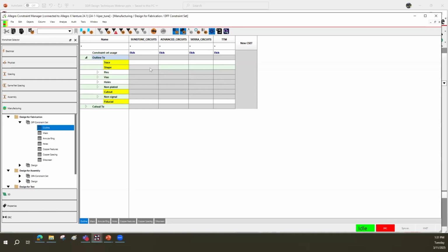Now, I've been around a while. I can remember days where I'd send my board file off on a Friday, expediting. I wanted to work on it over the weekend, only to come in on a Monday morning to open my emails and find a laundry list of things I didn't follow. It was their rules, their minimum requirements. This is taking that away. This is when you're done with your design, you're really done with your design because you're putting their rules in there and you're checking your design to their rules.